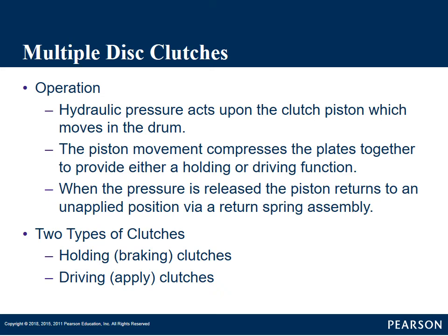So when we're talking about operation, we've talked about it a little bit. We're going to take hydraulic pressure through the passages in our transmission or valve body, depending on when we want to get a shift, depending on which clutch pack we use, which holds certain gears. And when we get into diagnosis, we'll go through what we call clutch and band application charts.